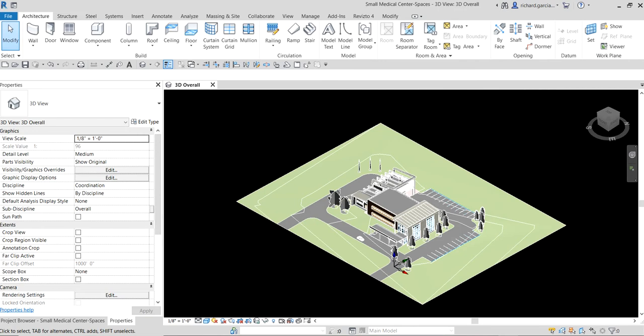In this video, we are going to talk about how to define the volumes in our project. You will learn in this short video how to place spaces for heating and cooling loads analysis to determine the energy demands of a building. Spaces are also used by Revit MEP to create an analytical model for building performance analysis.